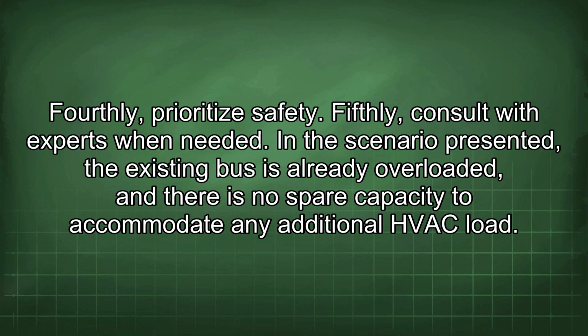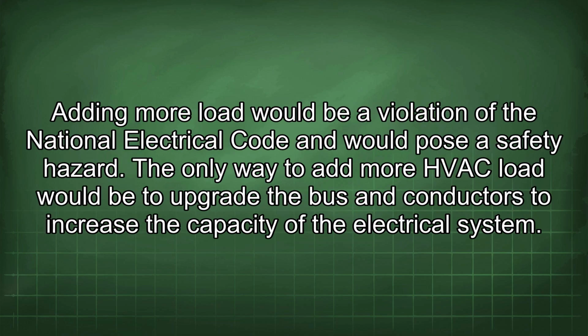In the scenario presented, the existing bus is already overloaded, and there is no spare capacity to accommodate any additional HVAC load. Adding more load would be a violation of the National Electrical Code and would pose a safety hazard.